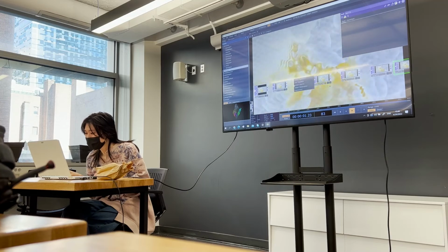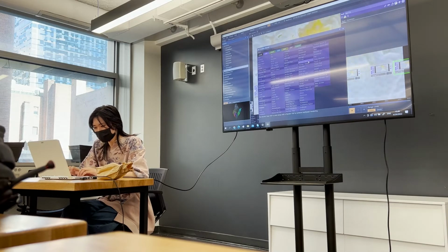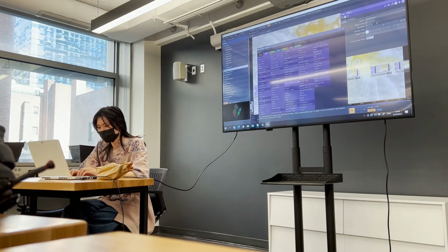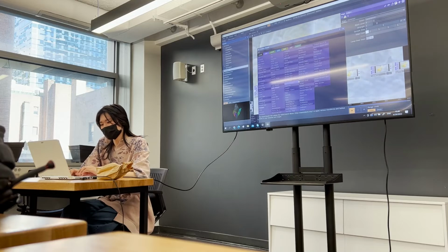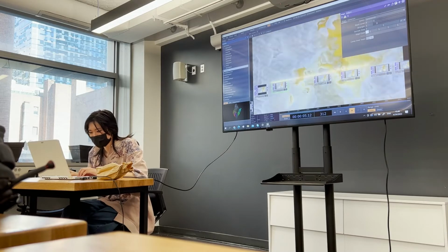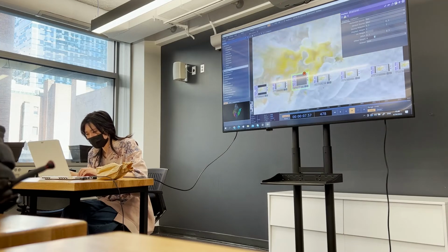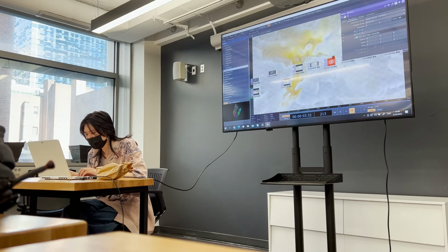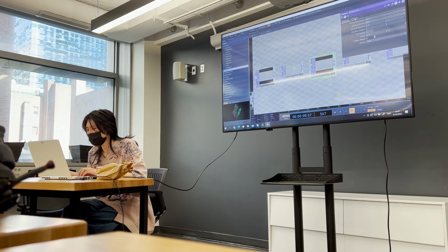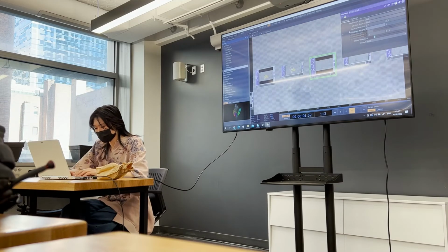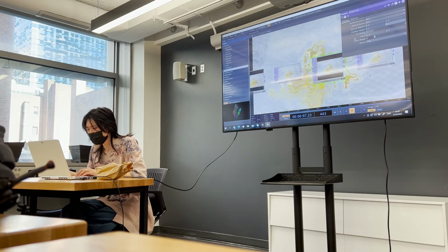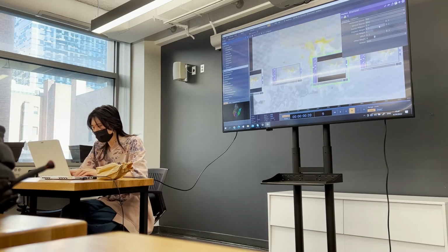in between these two, we can add another displace node to make the picture more distorted, as you can see there's like a cloud. But if you want it to be more organic looking, there's going to be another displace, and I'm going to plug the same noise into it, just why not? Oh, this is too strong. So I'm going to change the displace weight to 0.1 and 0.1. Slightly too strong. 0.01.